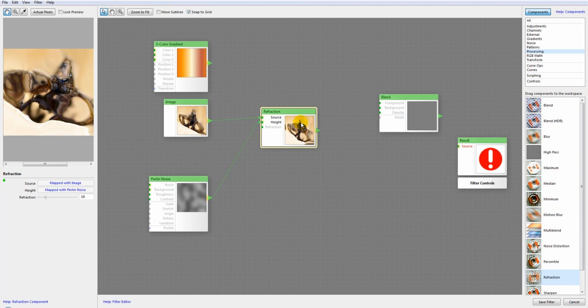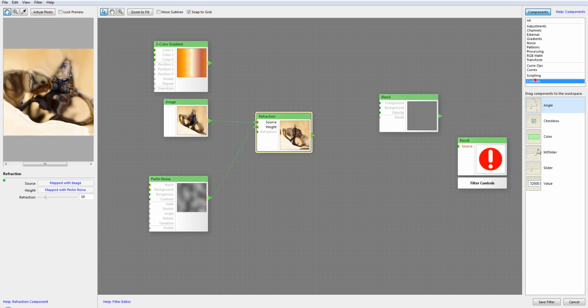But you can calculate by taking 100% and multiplying by 1 minus IOR1 or IOR2, so you can simulate it or come up with a mapping mode. In some cases, what I recommend if you want more accuracy is to use a control, using your sliders or other controls and mapping it directly with a function. In this case, just change the refraction from 1.0 to the more accurate refraction index that applies, and you can be very accurate.